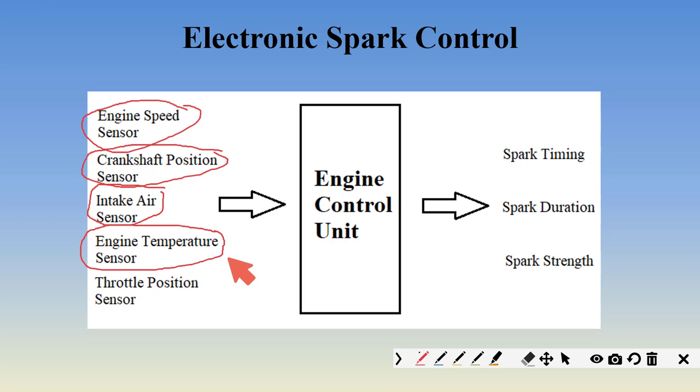Okay. Engine temperature sensor is required. Why is engine temperature sensor required? Because if it is cold starting conditions, in that case the quality of spark should be higher and the time for which the spark is produced should also be higher. Why? When there is cold starting, there is possibility that combustion might not start. Hence, the spark should be produced for a longer amount of time to ensure that the combustion starts.